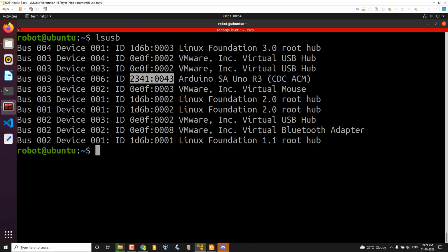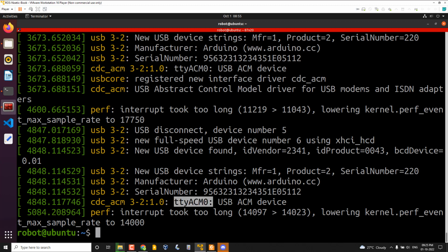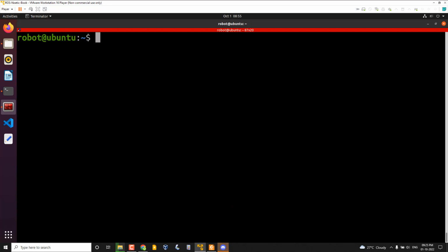Okay, there is another question from Rohan. So we don't have to use sudo? Basically, when you work with the Arduino IDE, this kind of permission issue is very common. Setting the UDEV file will remove that permission issue. I hope that is clear to you, Tejas and Rohan. By the way, what we have identified is that the USB is plugged in and the device file is ttyACM0.